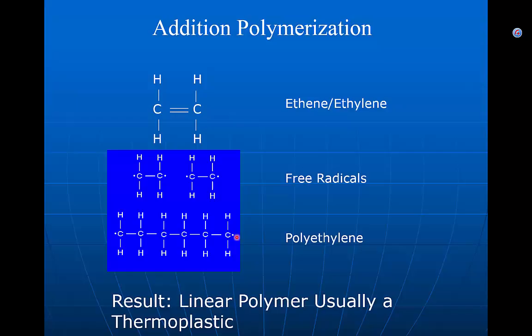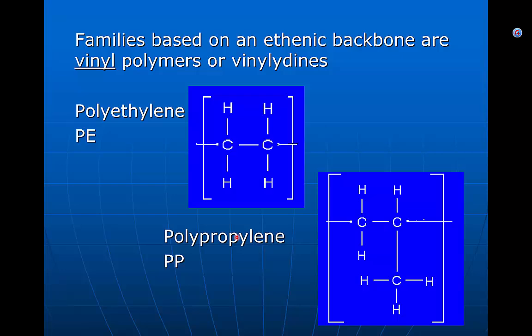Now, there's several categories of polymers. There are a number of structures. I want you to learn 4. You're going to learn the 4 simple vinyl polymers, the simplest of the vinyl polymers. And the simplest vinyl is polyethylene. This is my building block. The braces mean this is just a repeat unit, and we're actually going to build long chains out of this. But it's simply this unit repeated over and over again. Obviously 4 hydrogens, 2 carbons.